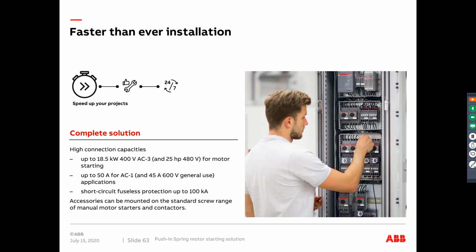We have a complete solution up to 18.5. This is especially for group mounting, or for example for control type of market, HVAC, where you have heaps of contactors, lots of fans, and lots of wiring to do. So this solution will save you heaps in wiring cost.